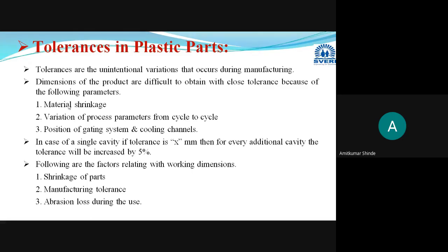So why is it not possible to achieve this? Because of certain parameters that are affecting the process. And what are those parameters? Generally these three parameters will affect whichever manufacturing process you are using to obtain the desired shape and size. It will be affected by the material shrinkage. Whichever plastic material you are choosing here, it will be subjected to some shrinkage, and due to that shrinkage during the processing,